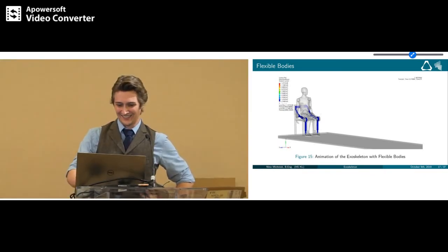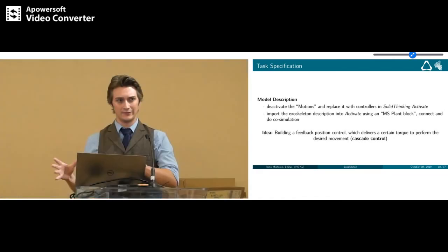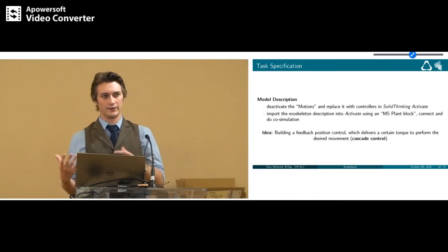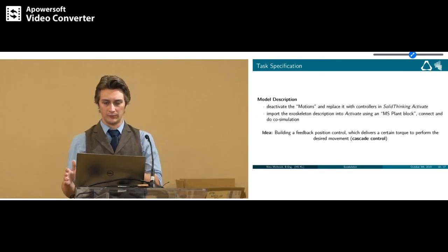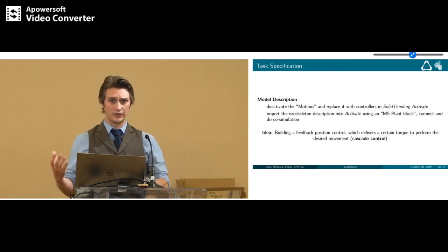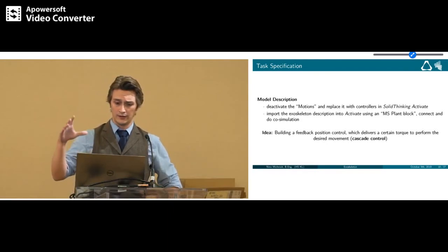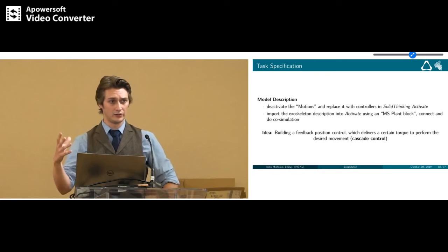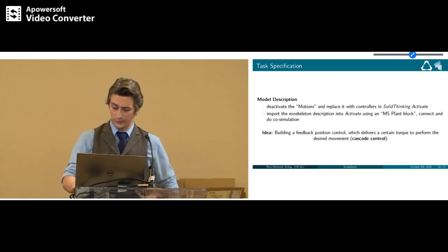Please don't ask me about the stress levels in the exoskeleton. And then, to quickly finish, I continued my work as a master's student in the so-called research and development module. And the goal here was to deactivate the motions I had and to replace them with certain controllers in Activate, and to perform co-simulation between the two software packages. And the idea I had was, because I already got these entire angle displacements for the movement, to build some kind of a feedback position control which delivers certain torque to perform the movements in the form of a cascade control.